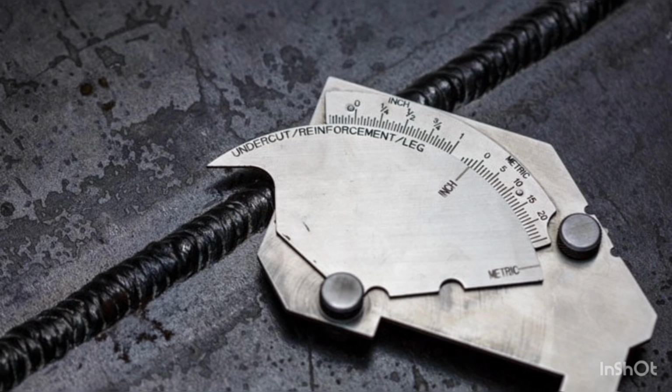Welding procedures are generally designed by engineers or senior and well-experienced welders. They're then tested to see that they meet the requirements of the code. They're tested for tensile strength, impact, Charpy tests. Sometimes other tests are required as well, depending on the code setting under certain conditions.